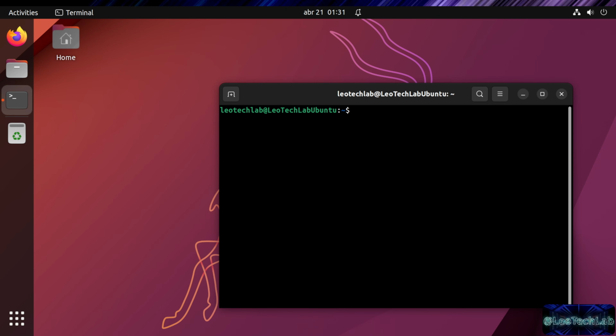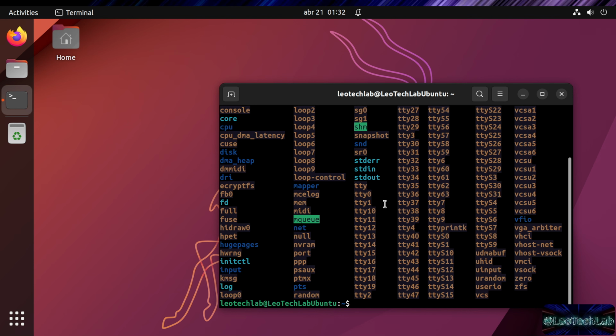Okay, this means that if I do an ls /dev, okay, so this is the devices directory, I should be looking at something like ttyUSB0 or ttyACM0. Okay, at least for my printer it's ttyUSB0. Okay, I'm running Marlin firmware on my printer, and I do think that several other 3D printers are the same, but yours could be different. Okay, but for my printer it's ttyUSB0.